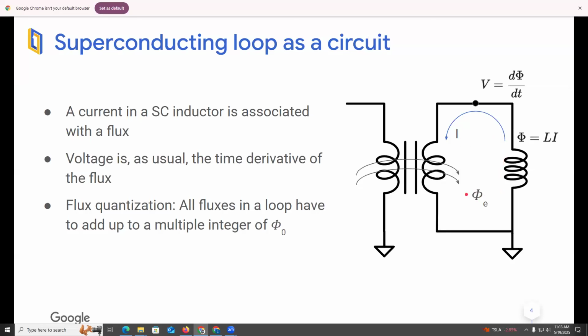And so when you're looking at this circuit, you already see that you might have a problem if you're going to try to simulate it with a solver. Because in DC, I can put some flux bias, and there will be a DC current flowing through. It's DC, so the voltage is going to be 0. Because the impedance of these inductors at DC is 0, you can have any current in the loop satisfy that condition that the voltage is 0.